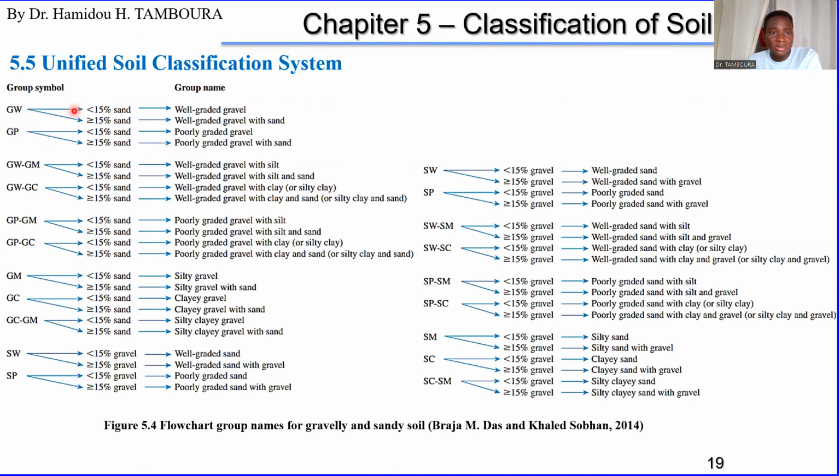You just read: well-graded gravel if less than 50% sand. If it is 50% or higher sand, then you say well-graded gravel with sand. In that case, the amount of sand is not negligible.